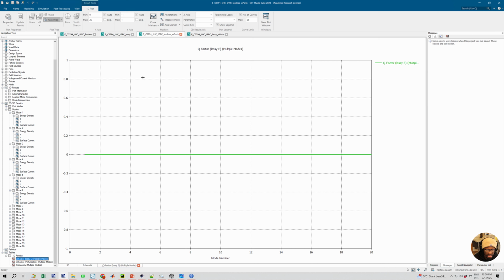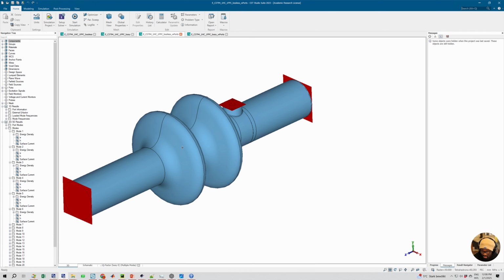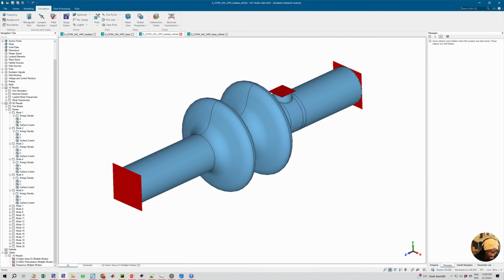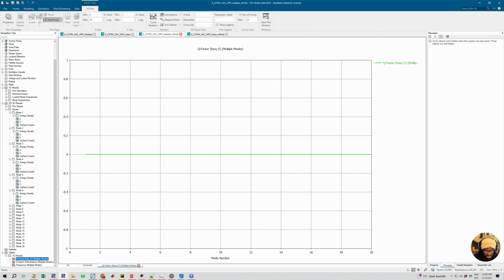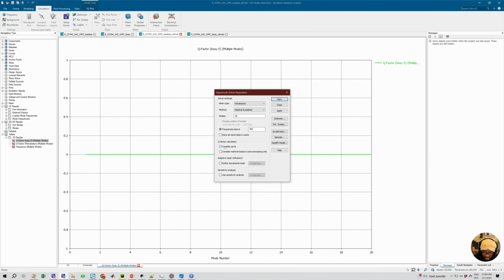Now if you check even including ports, I also ran the simulation just in case for lossless, including waveguide ports, and let me see what my boundary conditions are. Yes, also magnetic. I don't think it considers the waveguide port boundary conditions, because the external quality factor from this still returns 0, even though this is classical lossless, and even though I selected to consider ports in the simulation.